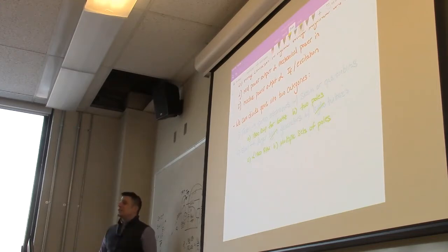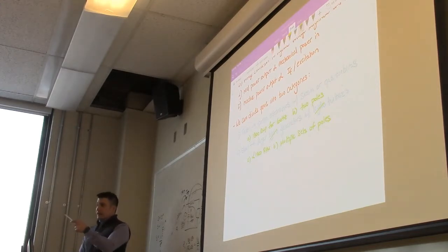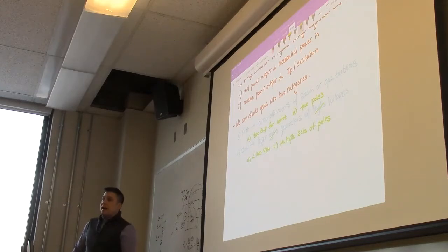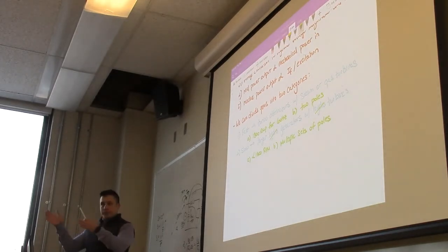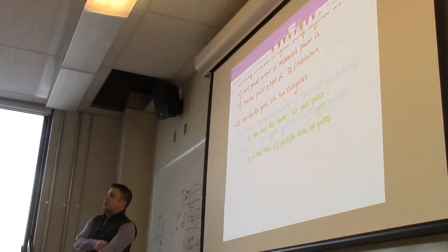And there's also shades of gray in between. Hydro might have 8 poles, 10 poles, where it's running much, much slower. And then there might be a steam-powered station which runs at 900 RPM and just has 4 poles, right? And there's a big difference in how far we can go with that train of thought.